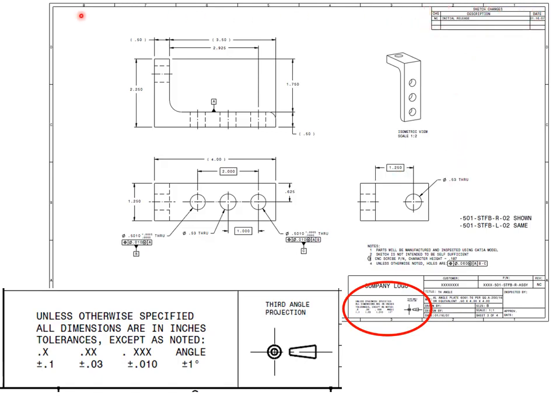So when you first release a drawing through document control, it gets processed, dated, signed off, everybody signs off, your supervisor, etc. Document control will sign off, and it's an official document, so think of it as a contract. Now, if a few weeks later you want to change the diameter of the hole, so here we have a 0.59 diameter hole, it appears. If you wanted to change it to a larger diameter, notice we have NC. NC is the original, which means no change. You could also use a dash or IR for initial release.